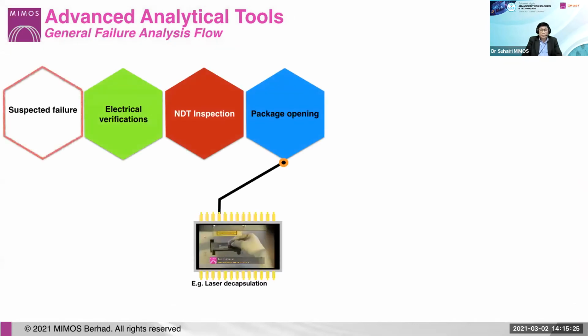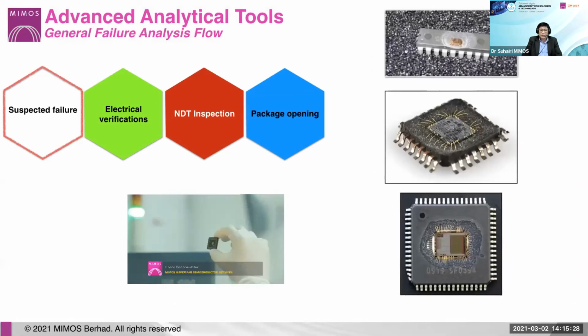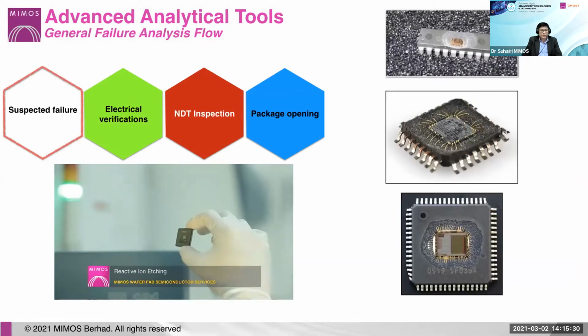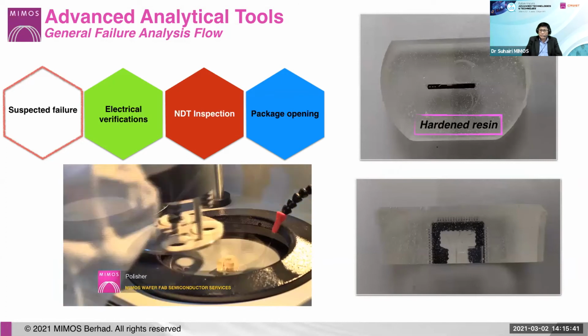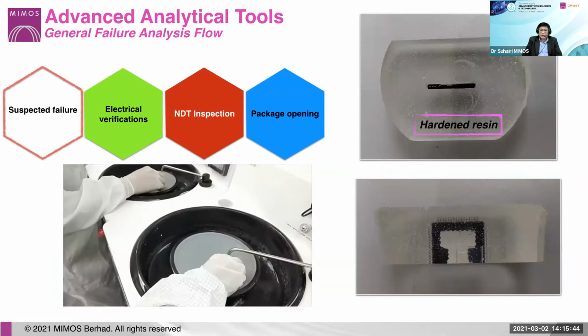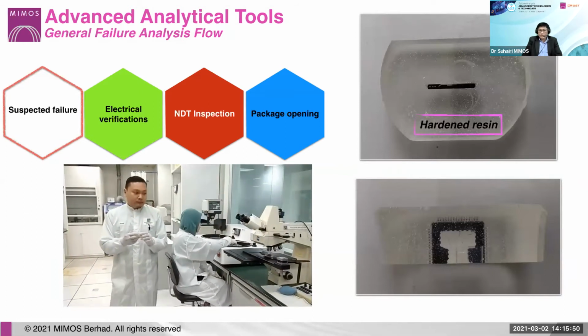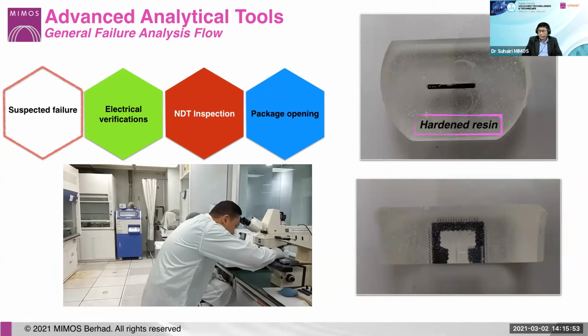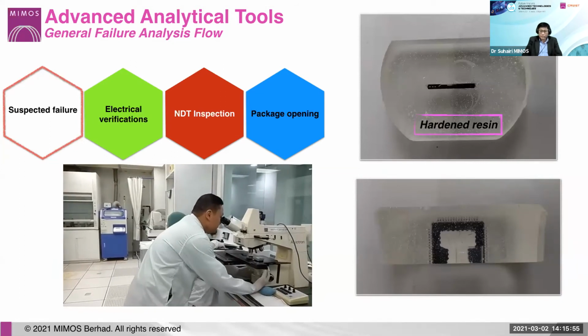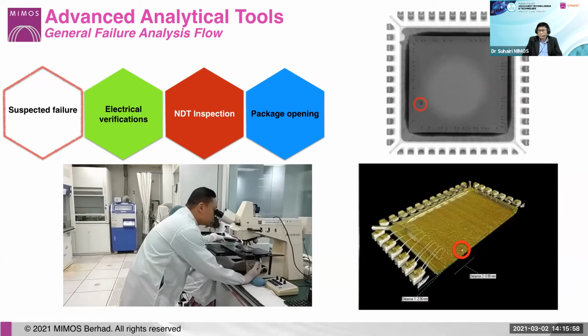For a situation when the internal structure of a device needs to be revealed or exposed for further identification of defects, we provide various techniques for IC package opening, such as wet etching or laser decapsulation. And sometimes human skill is still needed when it comes to locating a target in a device where a slow process of revealing defects in the IC is necessary. In this case, we offer mechanical polishing, which although crude and time consuming, is very effective when combined with our X-ray and 3D X-ray equipment, which make a difficult task such as exposing a defect easier.